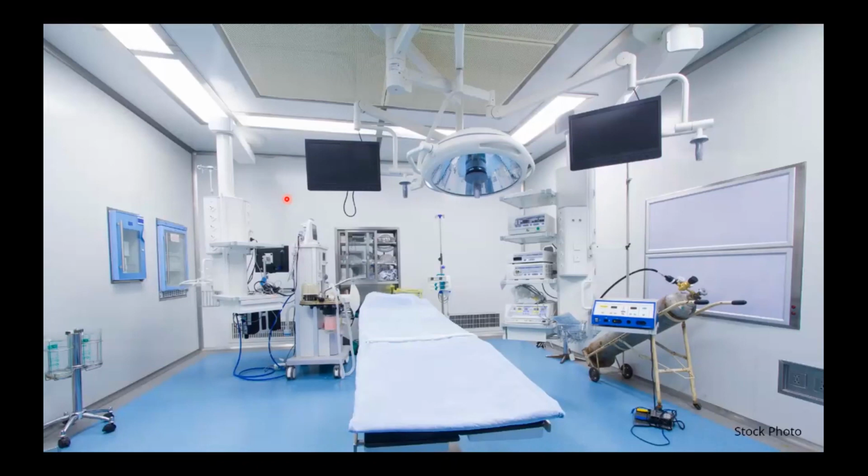Okay, so now we're getting some better examples. So here we see an operating room space that has laminar flow, that has more than adequate coverage for the actual table space. So we can see the laminar flow diffusers extend well beyond that 1 inch required by ASHRAE 170. And we see low mounted return grills. Now these look like they might be a little lower than 8 inches, but it's pretty good. The only thing I see is potentially just the level of the low return grills.